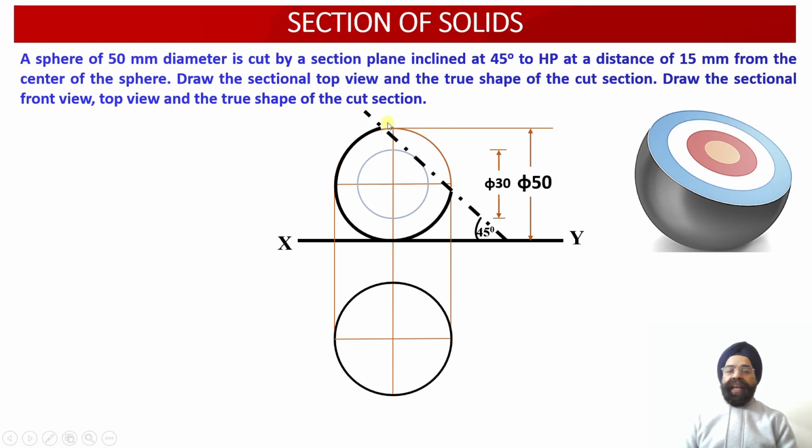Now we can divide the sphere into 12 equal parts as well, but even when we divide the sphere into 12 equal parts, most of those sectors which are separated by 30 degree will not be intersected by this cutting plane. So we will not have enough points of intersection of the cutting plane with the different sectors that we could have generated.